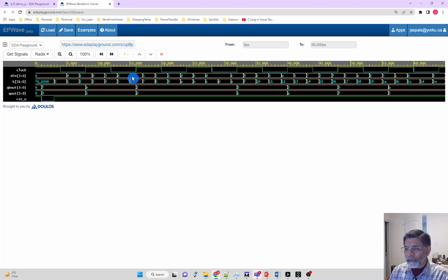This is a hexadecimal value, which would be, I think, 13. So that is D, and here again D, so it stays at that value. Here the input changes to C, which is 12, so it changes to C, and so on. Because we are using a 4-bit input, you can see the input has now gone from single bit to 4-bit input and 4-bit output.